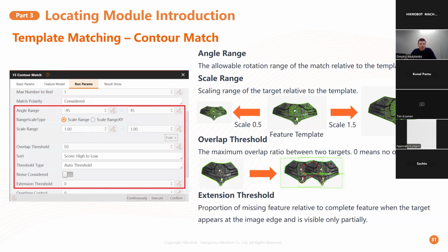By default, it is set to a rather narrow range of 90 degrees, and you may want to actually increase that range if you don't know how much your target is rotated. Overlap handling determines how closely multiple detected targets may overlap, with lower scoring results discarded when the threshold is exceeded. Usually, it's the object which is in the back, obviously.